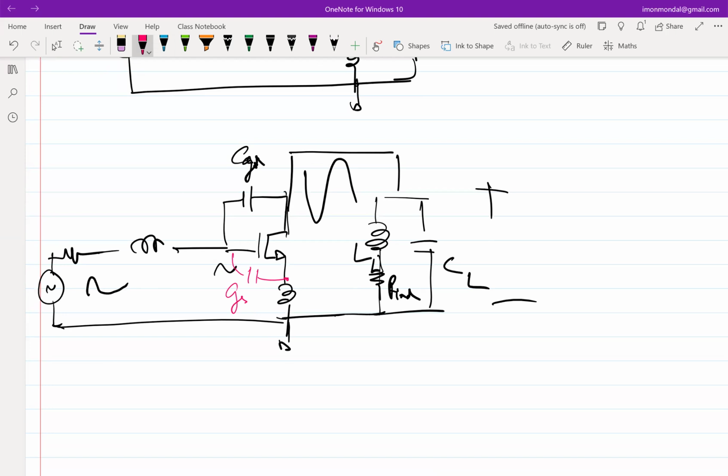Correct? So the input impedance is, I mean, CGD coupled with LS was giving real part, right? That was a matching part. So if I have another CGD which gives another real part, and these two come in parallel, which means the effective impedance goes down, right? So you design for matching, that goes for a toss.